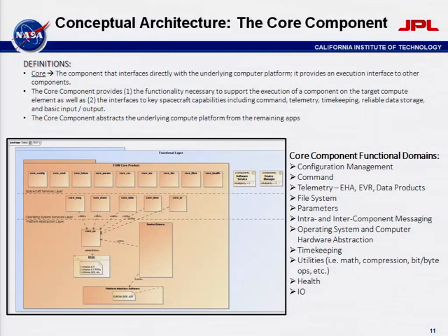Built on top of the platform abstraction layer is your operating system services layer. This is your basic operating system services. These are things that really aren't going to change from mission to mission. This really should stay and remain the same depending on what deployment you do. And this includes your messaging code, memory allocation, basic utilities, timekeeping, and your basic input-output.